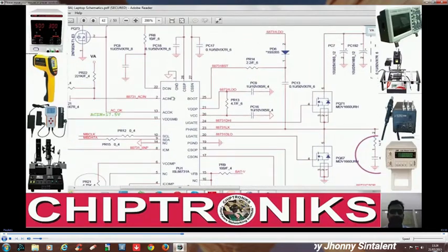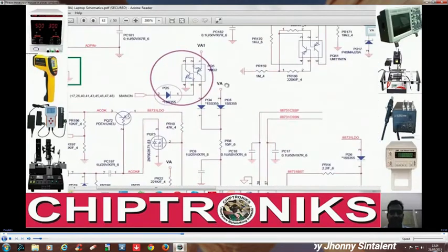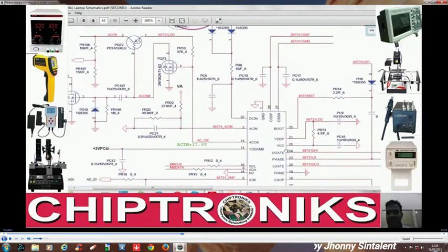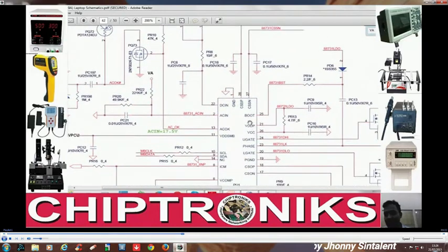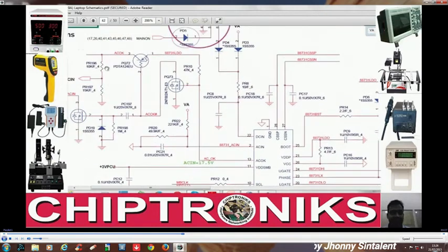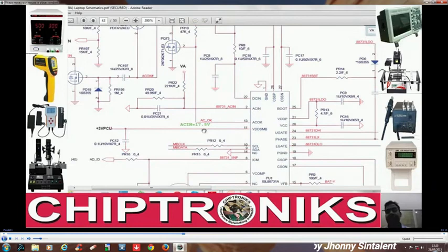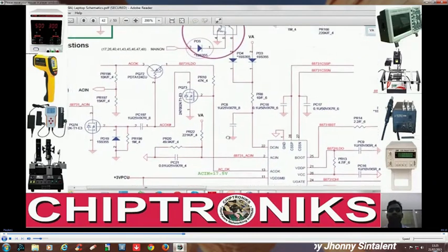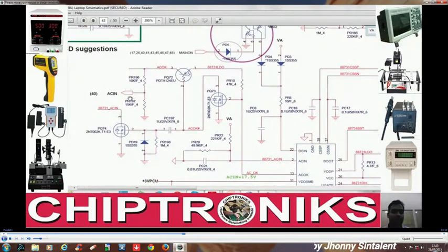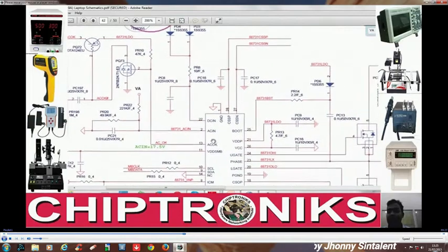This charger IC, the VA is going to the DC in, and it will generate an LDO voltage, so it will come across this VDDP. And the same VA through a resistance divider is going to AC in. So this charger IC will give a digital output of AC_OK, and it will go to create an AC in signal, and that will go to the IO controller, right? That will go to the IO controller.